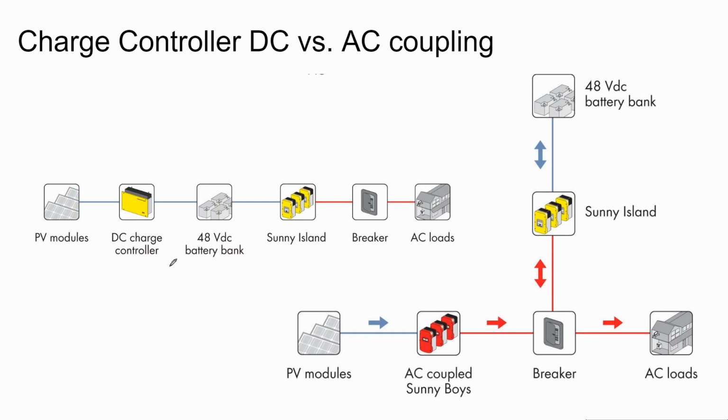There's also an issue of voltage to consider. I think we'll talk about that a little bit later. But this is where the lithium-ion systems get to be a little bit more efficient, because we have to remember the solar array is done at 600 volts typically. If I have a 48-volt battery bank, there's the efficiency loss in getting from 600 volts down to 48, and then I'm going back up to 120, 240.